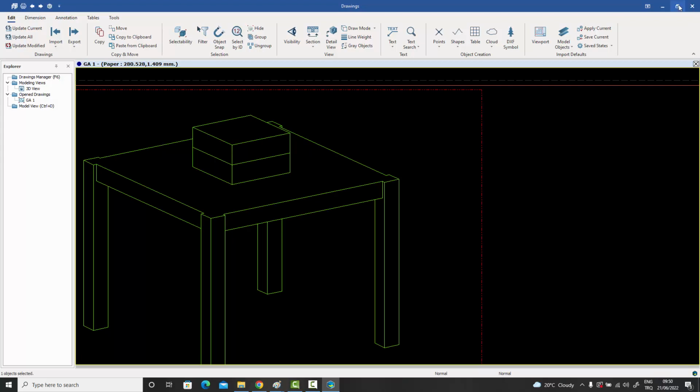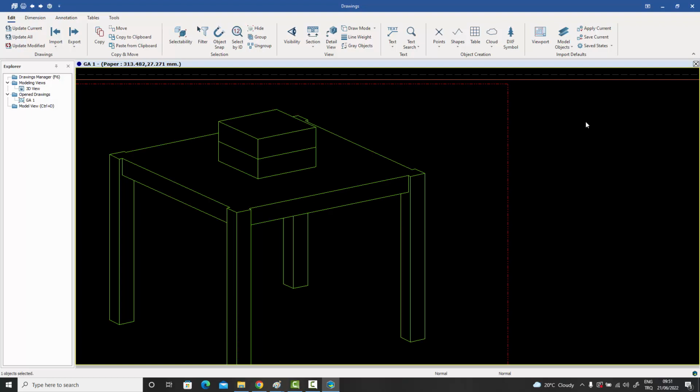Well, that's true, and you can do that. But sometimes when you have very thick slabs, for instance, you might have a foundation slab which has a thickness of say 2 meters or 3 meters sometimes. In very heavy industrial plants, those kinds of thicknesses are possible. And you cannot pour the slab in one go, and you want certain lines to appear between the two, the pour lines. So you can divide those into separate formwork groups.